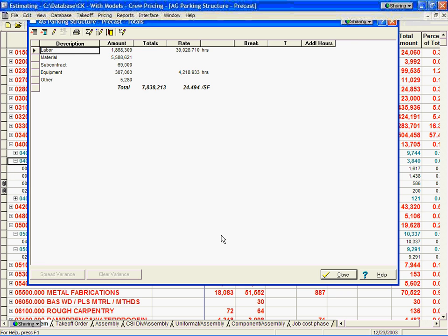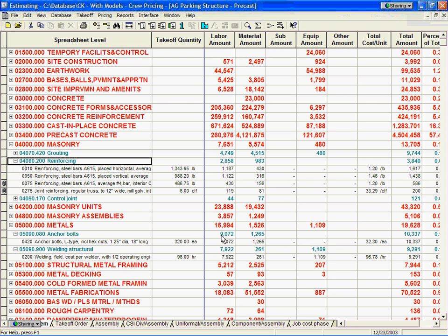So based upon that, once we figure out a price or a capital budget on this thing, what we want to do is have the ability to refine that. Someone else may come back to us and say, well, what if we did that above-grade parking structure, but instead of using precast concrete, what if we use structural steel? How would that affect our capital budget? So what we're going to do is take a copy of this estimate, and change some of the values in that conceptual control quantities to reflect that we want a structural steel number rather than precast.